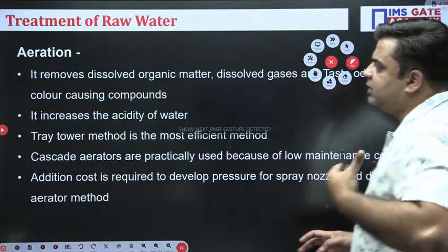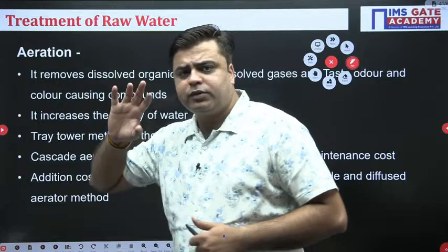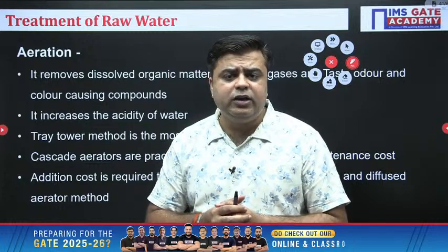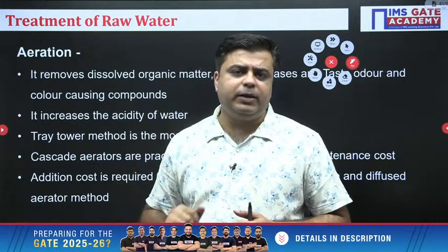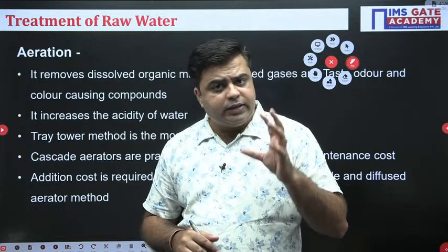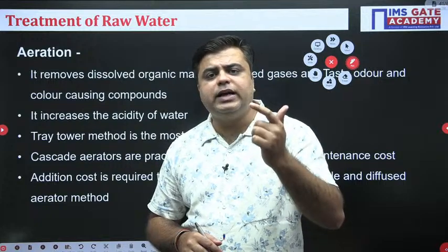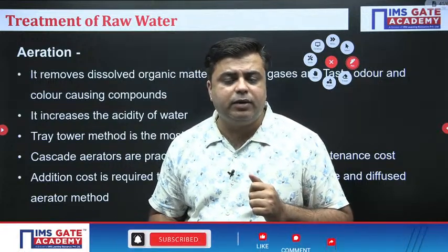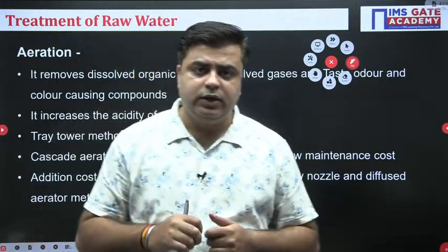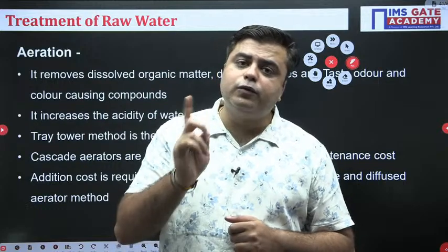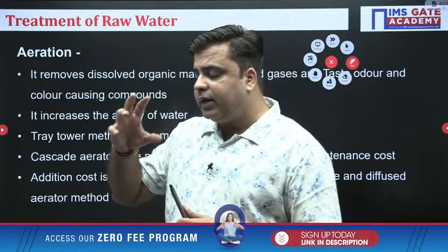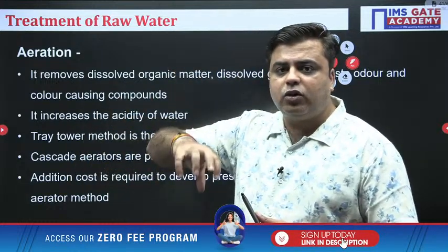Okay. The second method of treatment is aeration. The process of aeration is bringing the water in intimate contact with the air so that the exchange of oxygen from air to water can take place. This oxygen helps in oxidizing the organic matter present in the water sample. This increase in dissolved oxygen removes taste, odor, and those solids which cause all these things.